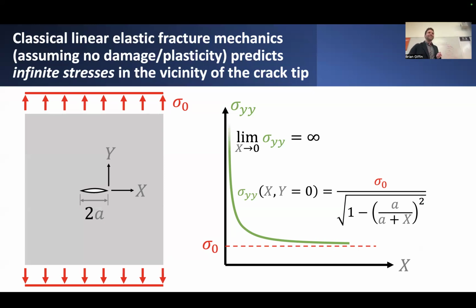Imagine trying to set up a finite element analysis problem of exactly this scenario. You have some kind of plate. It has some initial crack in it. Maybe you mesh the heck out of it even. You put a whole bunch of elements in the local vicinity of this crack tip because there's probably going to be some stress concentrations there, so you want to resolve what the local stresses are. And you might be tempted to say, well, I can just look at the element right next to this crack tip, measure its value, and then assess: does the stress in that element close to the crack tip exceed that critical threshold, that maximum stress at which we said fracture should occur?